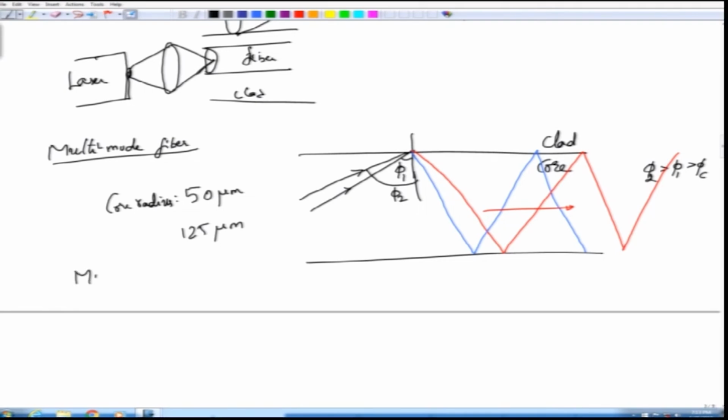Now, one aspect that becomes very important when you are looking at multi-mode fibers is what is called modal dispersion. This modal dispersion simply means this. Suppose I take a pulse of light and then I launch this light into the fiber. Let us say both modes get excited, that is light energy goes into both these modes, and then these modes will propagate along the fiber. You can clearly see that these modes are propagating along the fiber at very different velocities, and then when they arrive at the receiver, when you put them back together, you will see that the pulse has kind of expanded.